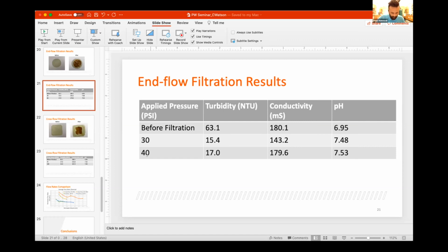In slide 21, once we treat produced water, we need to understand the mechanism, how we can remove salt, how we can remove the oil component. In this case, did you measure total dissolved solids, or total organic carbon, after treating the produced water, or did you just measure the conductivity?